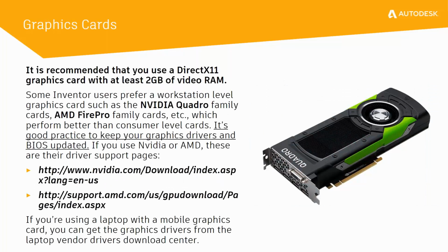When it comes to graphics cards, it's recommended that you use a DirectX 11 graphics card with at least 2 gig of video RAM. More commonly, we find that Inventor users are using NVIDIA's Quadro or something like the AMD FirePro. It's also good practice to keep your graphics drivers and the BIOS updated as well.